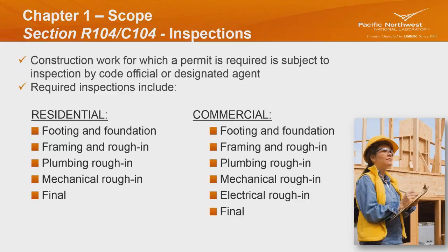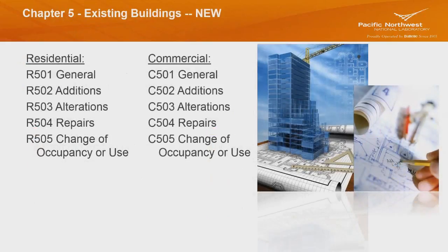So you would see a footing and foundation, a framing for the rough in, plumbing, mechanical, and then a final. And there's actually provisions that the code plan reviewer and inspector would go through and check off depending. So not all those will apply depending on what you're doing with your project, but it's important to know that each one of these, or maybe all of them, might be applicable to your project depending on what's going on.